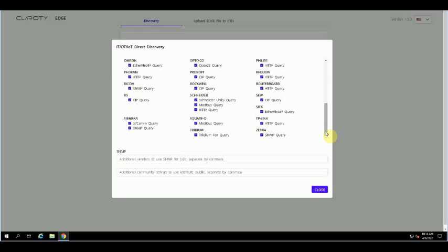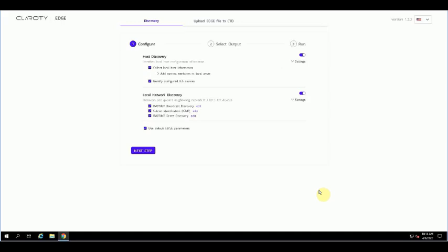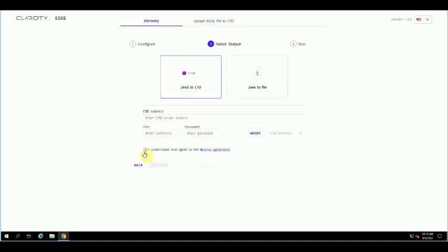Also, I've said before that these queries are type-specific. So let's say I want to run a Schneider query. That query will only target Schneider machines. It won't run on, for example, Windows-based machines or on Rockwell PLCs, because neither of those types are built to handle Schneider queries. Now that I've defined the parameters of the discovery, I can start the next step.